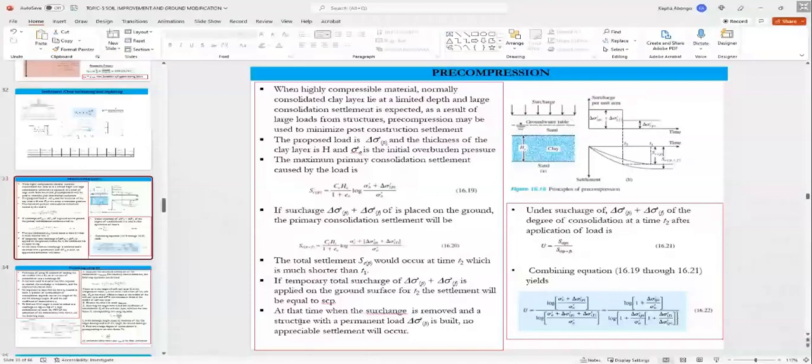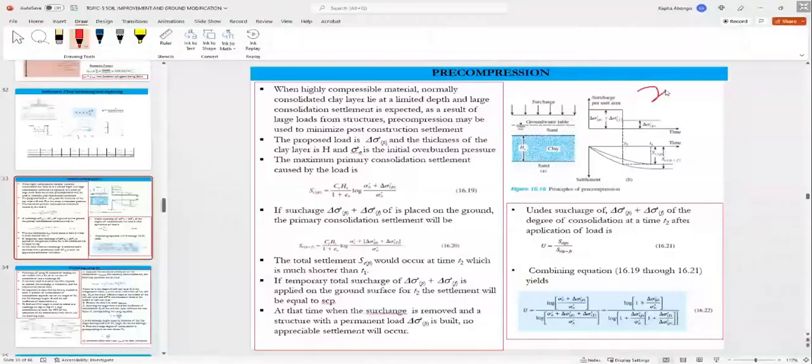Okay, that's one. The other property of fine-grained soil will be the issue of permeability. It has very low permeability. Some of these are in the order of 10 to the power negative 7, negative 8, negative 9 centimeter per second. So very low permeability. The issue of permeability means the water drains through those soils at a slow rate.